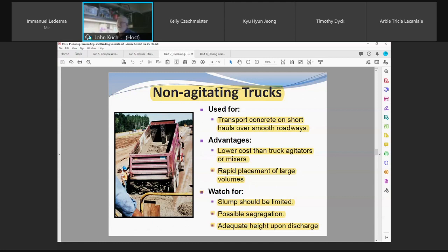Plus, if you're working in a congested area with overhead power, check your overhead. Can you boom up? Can you lift this truck box up to dump in front of the paver? Or is he contending with hydro lines, whatever the case may be, towers? Okay, so there's some pluses. There's also some negatives, but great for large volume jobs. Ideal.